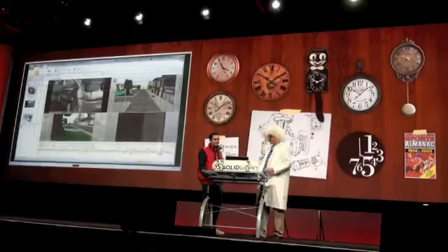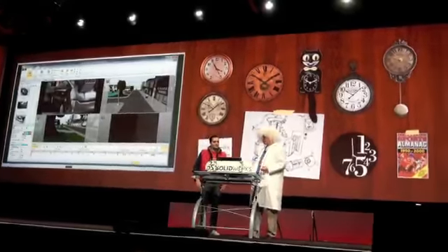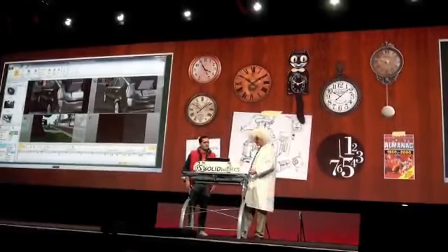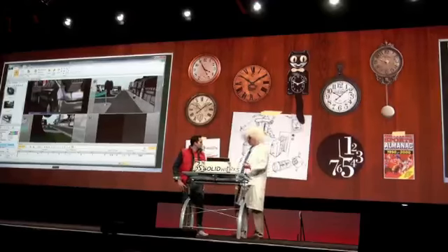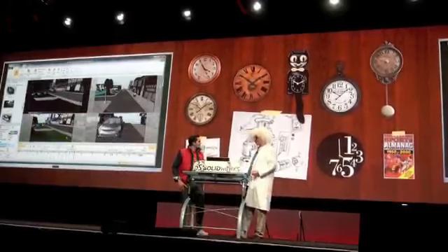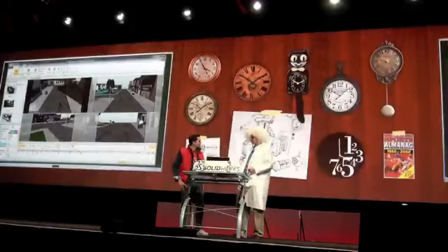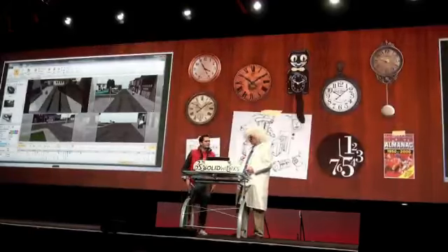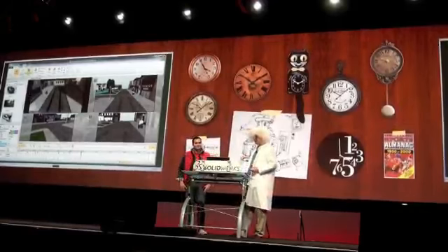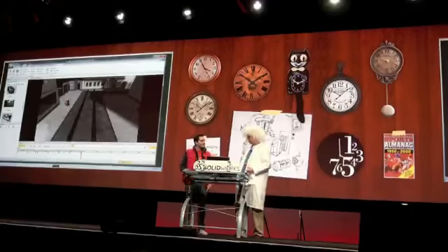And speaking of that, I thought I'd use 3DVIA Composer 2012x to show how you're going to return. You know, using the new support for multiple cameras, we can track the action as you head down the street. We can create shots from any angle, as well as adjust the camera or target position at any stage. Now, the flux capacitor should kick in just as you reach those light posts, so avoid taking out the building on the corner. But for some extra polish, we can also adjust camera views along the timeline of the video, and that provides some truly stunning footage of your departure.